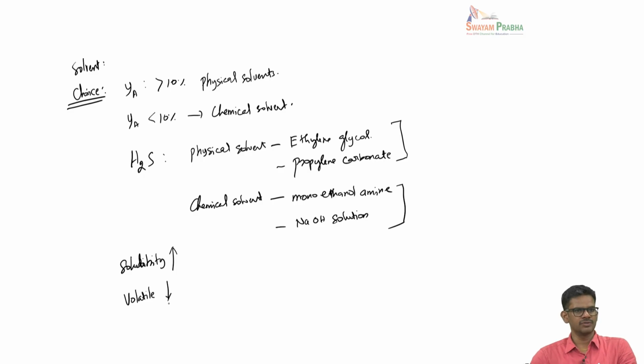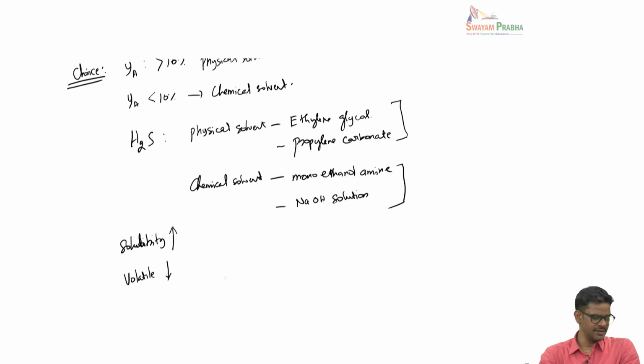Yes, apart from the solute, the liquid solvent will also get exchanged into the gas phase. Then you are talking about multi-component absorption desorption issues. So, we want the solvent to be as non-volatile as possible. It should not have high vapor pressures. So, the volatility should be less.